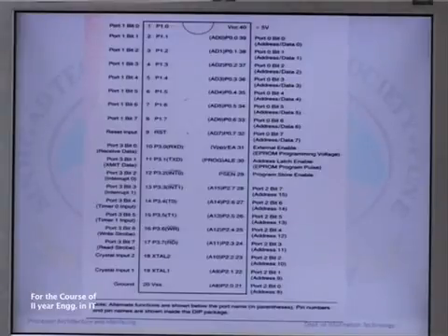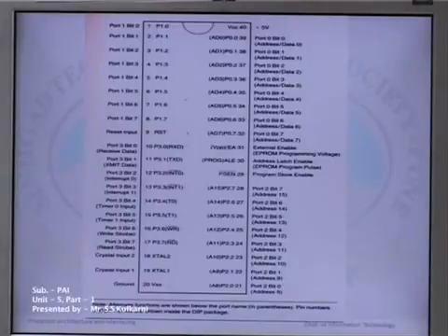As seen, port data multiplexing is performed by means of only one additional integrated circuit. In other words, this port is used for both data and address transmission. Port 0 is used for transmission of data and address both, and the demultiplexing of it can be achieved with the help of the signal ALE, which is nothing but pin number 30.